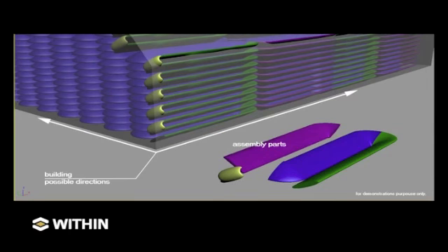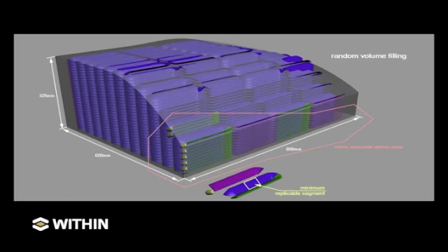This actually makes it amenable to being manufactured in countries where labor costs are much higher, because there's not much labor. Now, because this was designed digitally, you can assemble it digitally to fit any shaped volume. So in a Formula One car, you don't always have a nice big square block of volume to put your heat exchanger in. You have an awkward corner in the back, and you want to fill it in there. What you can do is replicate this to fill that corner to whatever space you have virtually, manufacture it or 3D print it in one piece, and just put it in there to fit.